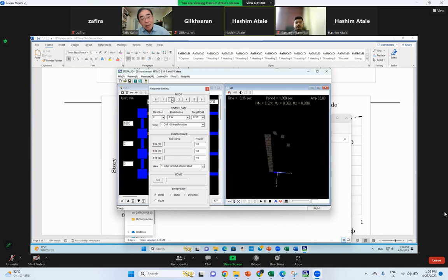They can move because it is tuned to the specific frequency of that TMD. As such, only this TMD shows the mode, and the top TMD doesn't contribute. So each TMD doesn't contribute to the mode vibration of each mode.